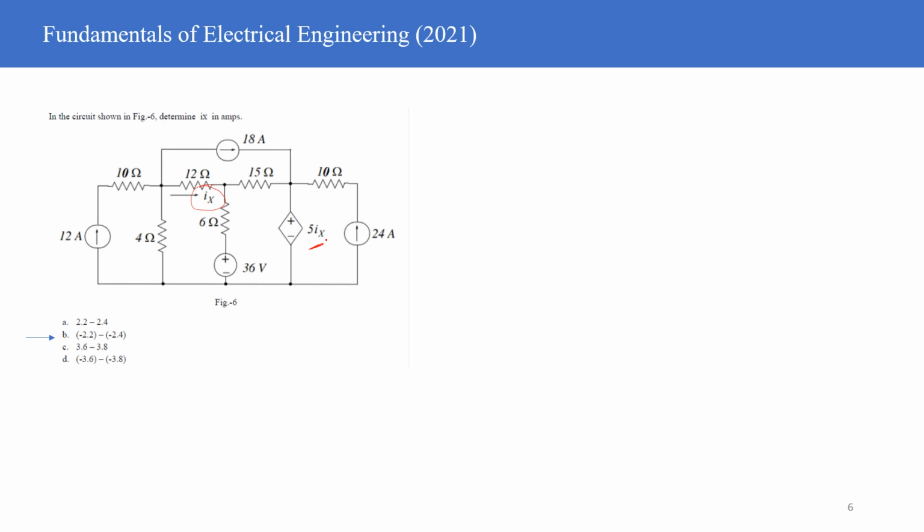So it's a dependent source. What kind of dependence does it have? Is it a voltage dependent source or a current dependent source? Voltage, DC voltage source, sir. It's giving you out a DC voltage, right? But it is dependent on? It is dependent on current, right, Venkatesh? So it's a current dependent voltage source.